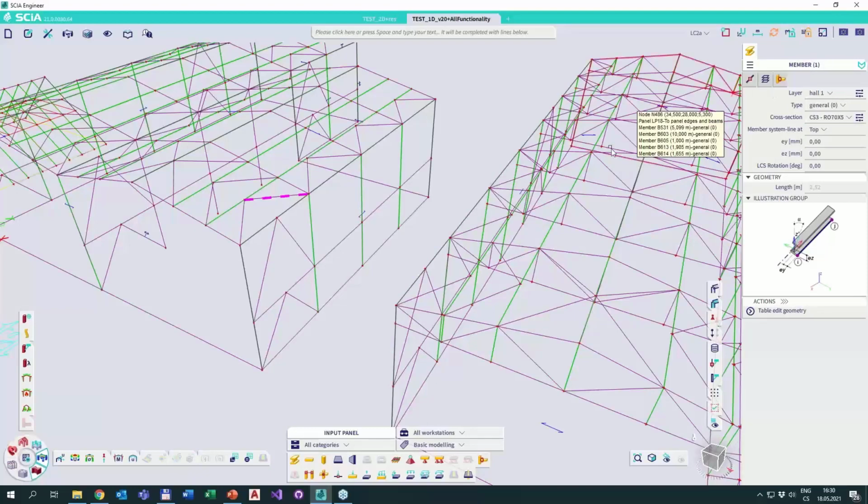Furthermore, very important aspect that we felt actually required some extension is the possibility to be able to quickly select objects based on the same property, whatever that property is. In this case, there is no special button here, but you can just right click on the property. Let's say that I want to select all the beams in this project with the same length.